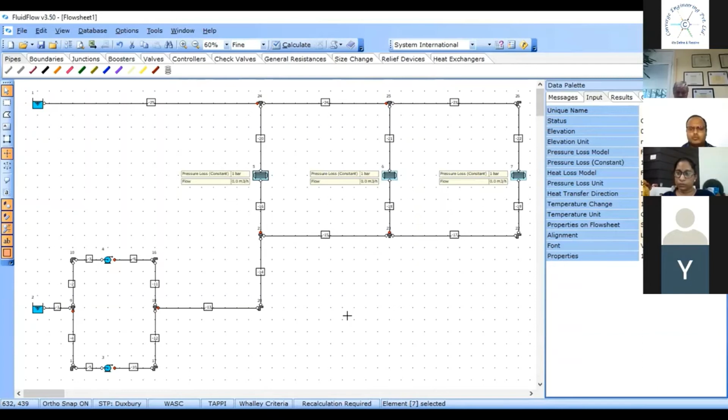Okay, so let's assume that we had done the Aspen EDR simulation for these 3 exchanges, and we found out that each of these exchanges needs 100 meter cube per hour of cooling water, right? Now our pump, we have got 2 pumps there, but one running, one standby. So what will be the capacity of each of the pumps? It will be 300, because there are 3 exchanges.